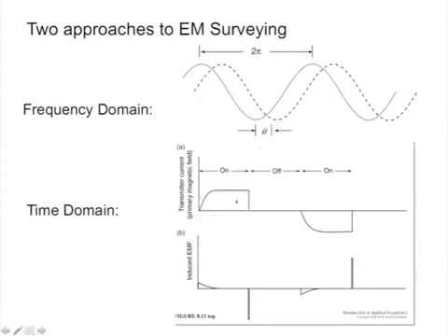The other thing is we can have a transmitter current, and so we set up a constant magnetic field which is extending into the ground, and then suddenly we shut it off. Okay, and we go maybe another fifth of a second or maybe a couple of seconds, and we ramp up the current in the transmitter again.